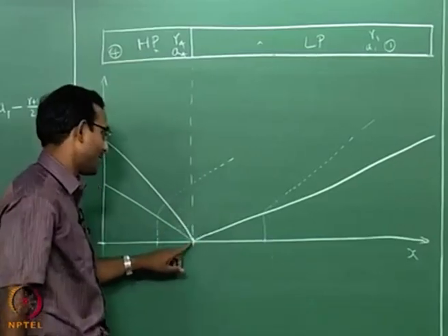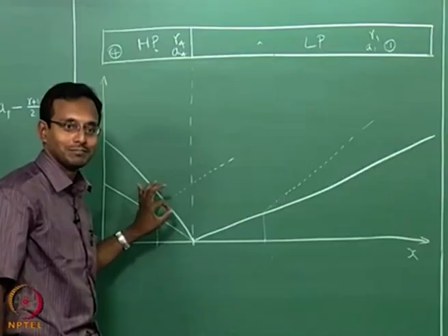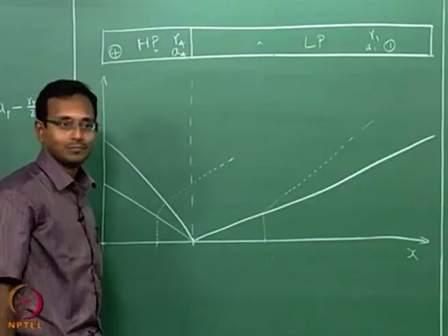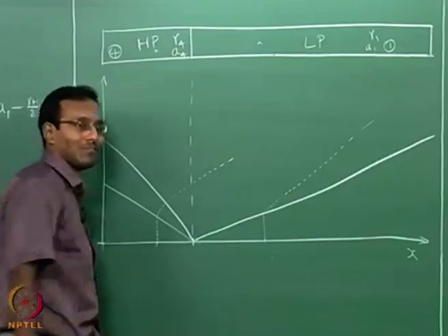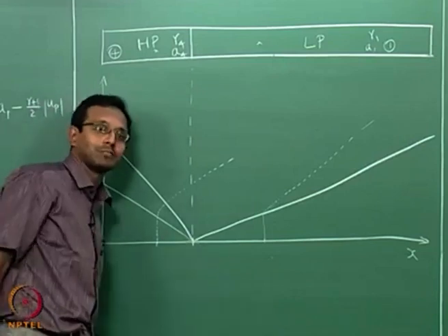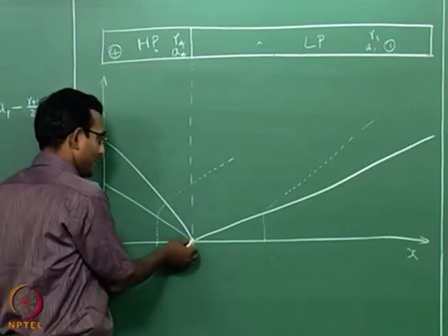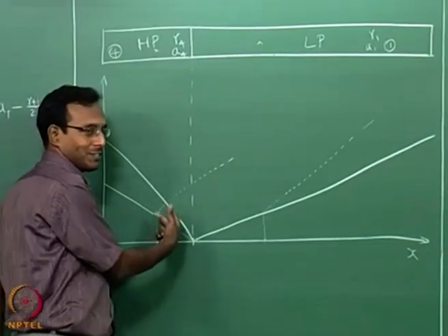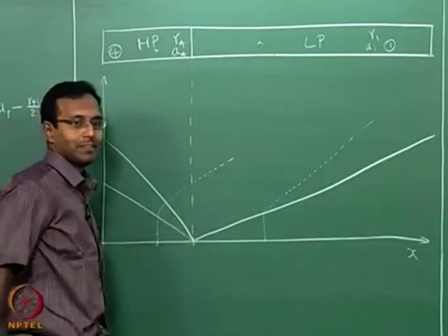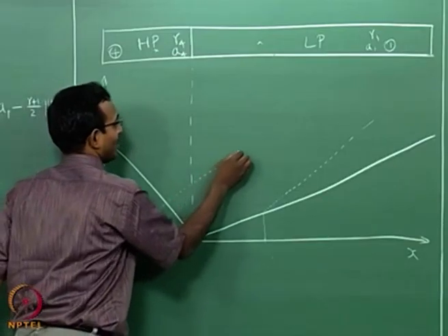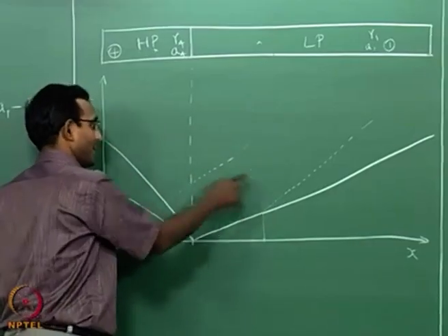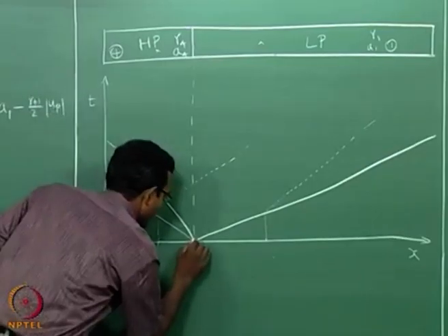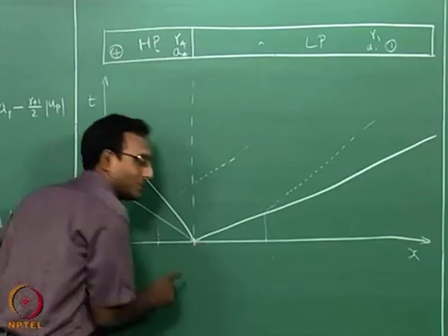I am going to assume it is a single point and everything is already discussed and assumed, fixed, okay. Fluid element immediately calculates all this and puts it out there, that is what we will assume, okay. That is a small assumption, it works reasonably well for our cases, we are not interested in that small time scales, okay. In a very short time, probably within a microsecond or two, the strength of the shock, how much expansion fan should be there, all that are decided within that time. Okay, and finally what should be the velocity of the fluid element behind the expansion and behind the shock, everything is set by them, okay. Ideally it is not set when it is this far, it is set for that particular fluid element very next to these diaphragms.